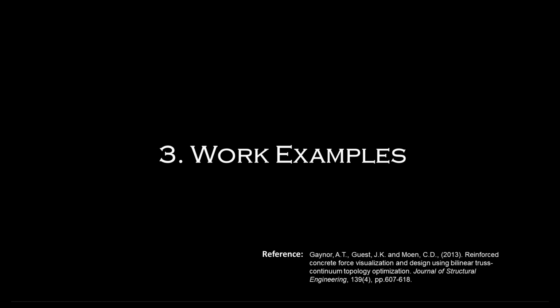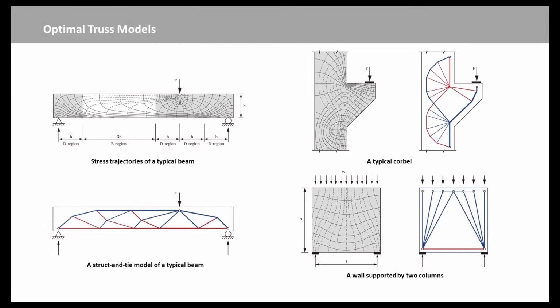Now we can use this method to optimize worked examples. It should be noted that in many cases, it is possible to draw a workable approximate scheme of load transfer without the knowledge of the exact linear elastic stress trajectories. In the previous cases, we can use truss layout optimization to obtain the optimal truss models, which can be efficient and convenient to present the load paths.